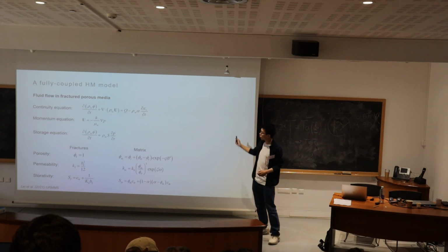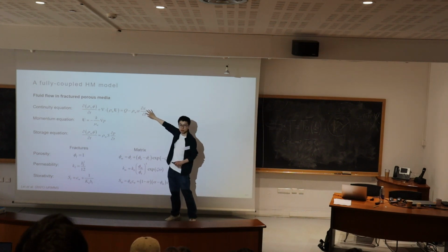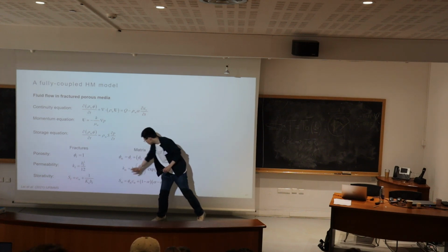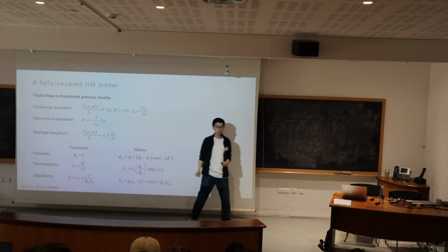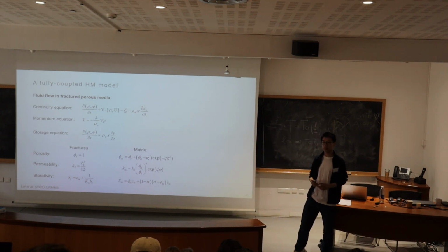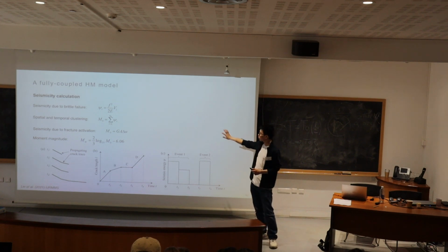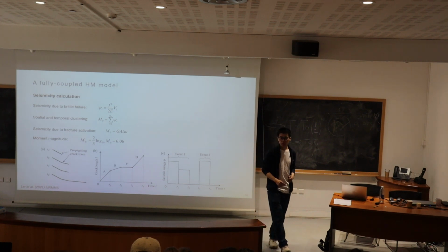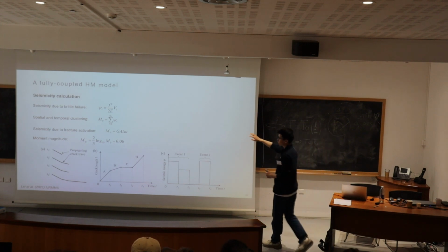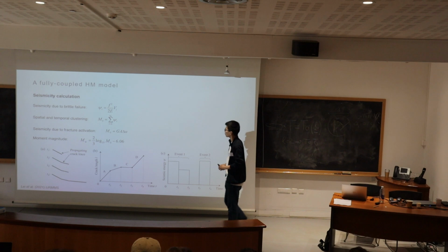And I further solve the flow equation with both the direct coupling through the volumetric change, poroelasticity, and also indirect coupling through the aperture change or the porosity changes, etc., to have both effects considered in the model. I further compute the seismicity evolution in the system using classical earthquake equations to compute the magnitude of the earthquake.